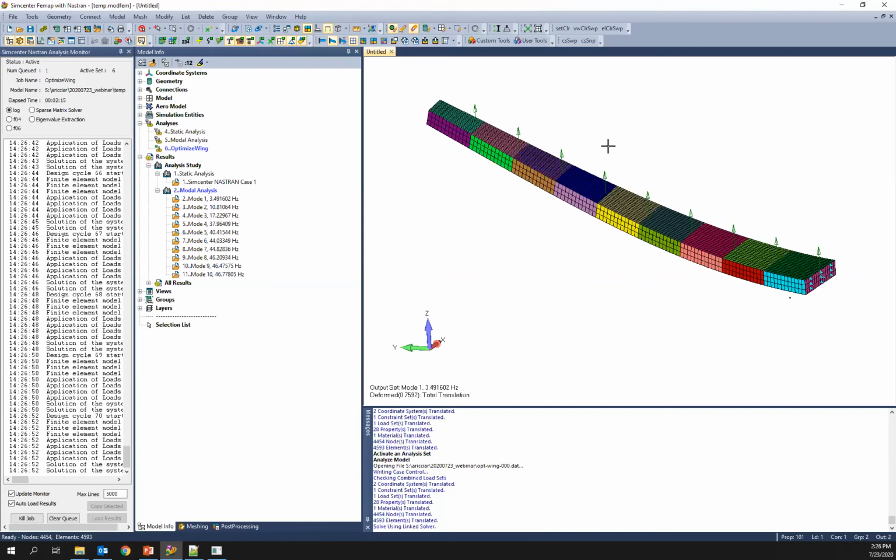No, there's generally not. You do want to be careful with topology optimization on certain types of loads, because of the nature of that type of problem. If you specify a load, like a body load that applies to the entire mesh, the optimizer's going to have a hard time removing elements because you have load applied everywhere. But for design optimization, there should be no problem, like a gravity load or some other type of body load. I'm not aware of any limitations on that generally.